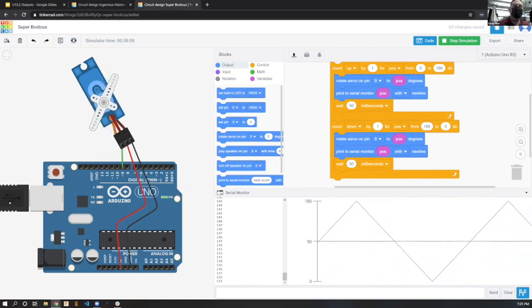A servo motor like that, if you give it a command, it'll try and get to that position, and it'll try to stay there. So if it's holding up a flap and there's a pressure that's down on it, it'll keep trying to push it up because it's got feedback about its position. So these can be really helpful if you want a motor where you're saying, go to a position and stay there. It will do its very best to stay there. You can definitely overwhelm them, but it's a really interesting way to try and get some motion that's controlled.